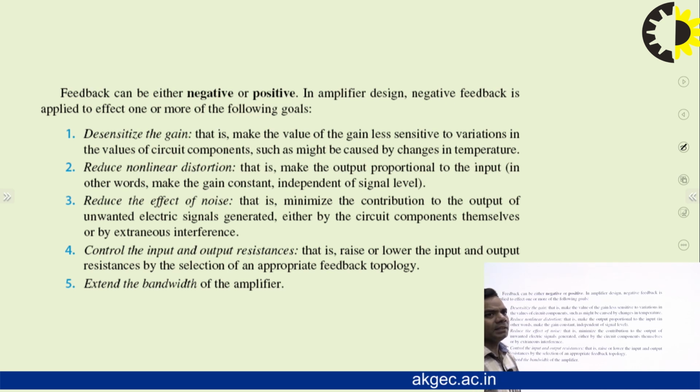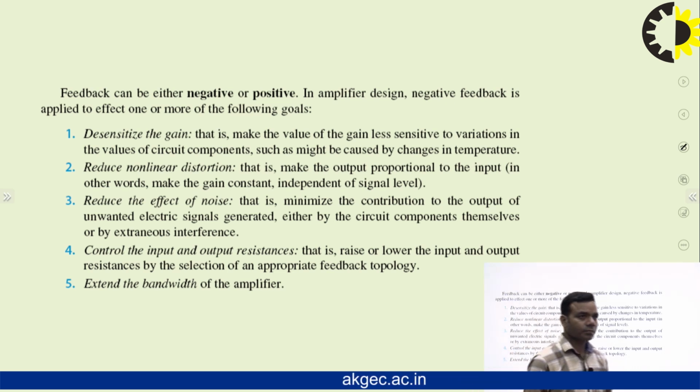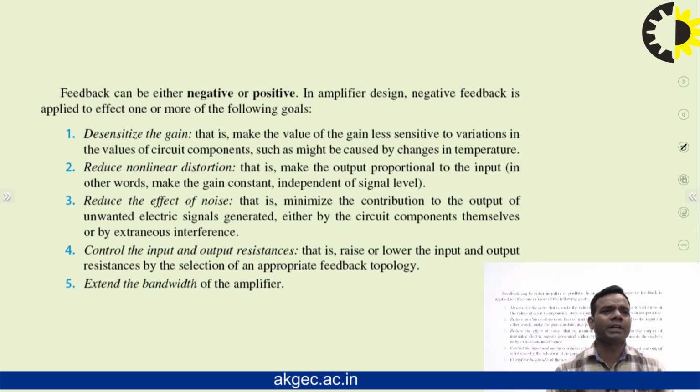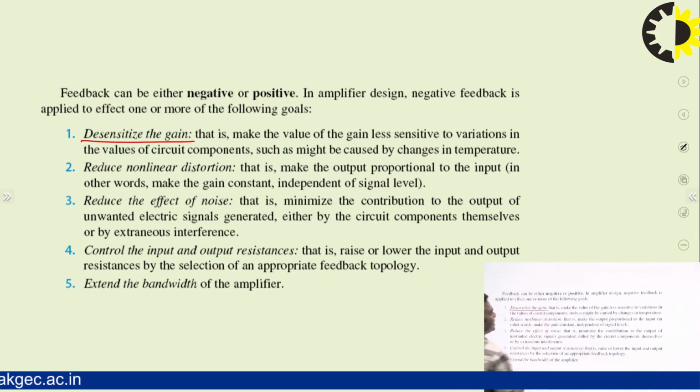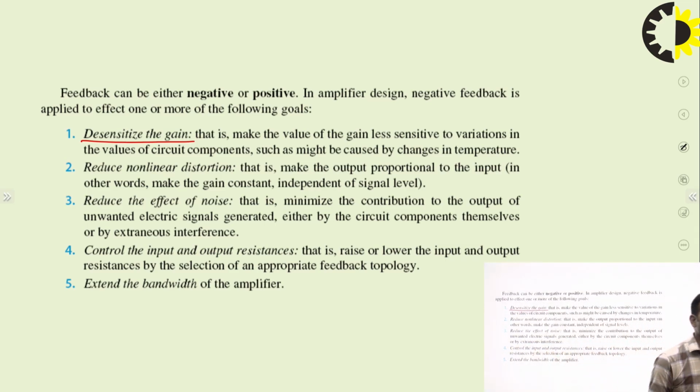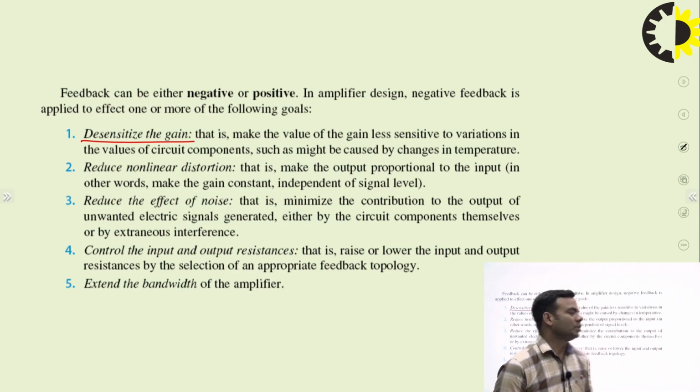Generally, negative feedbacks are used for the amplification purpose due to some advantages. Like it desensitizes the gain. That means the value of signal gain is less sensitive to variation in the value of circuit components, such as might be caused by the change in temperature as well as some other things.